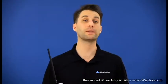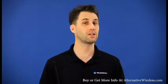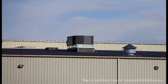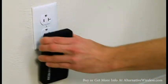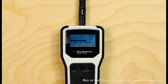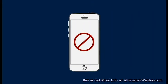Before I move on, I want to mention one issue that you may run into. The signal meter will measure all RF energy in the area. It won't differentiate between cell signal and any RF noise that you might be experiencing. Many pieces of equipment like AC units, transformers, and AC outlets can emit RF noise. If strong enough, the signal meter will pick this noise up and display it on screen, leading you to believe that you have a strong cellular signal. If you notice that you have a strong incoming signal level across multiple channels on the signal meter at a location, but are unable to place a call, or the signal on your phone shows up weak, then this is most likely what is happening.